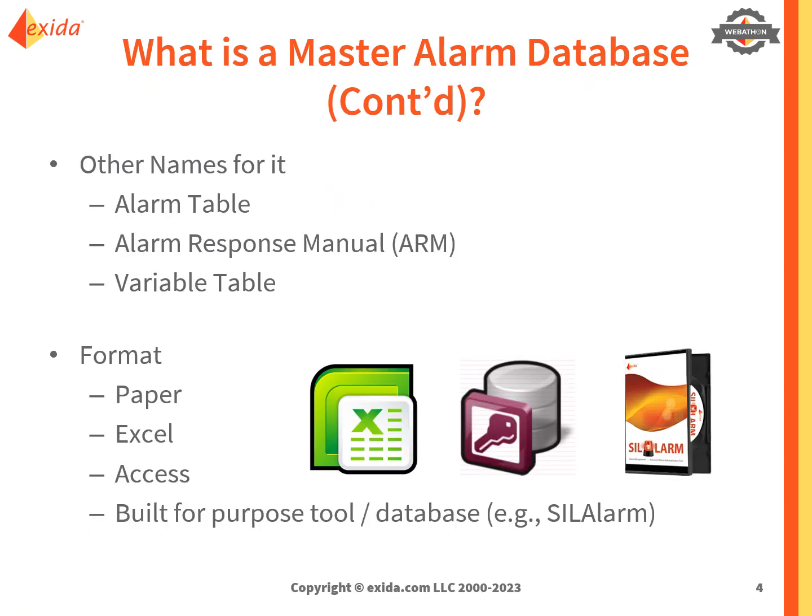Now, a lot of people call the master alarm database by other names, such as an alarm table, an alarm response manual, or a variable table. But one of the advantages of a standard is that it establishes an agreed set of references and names which everybody understands, and in doing so avoids ambiguity. Now, there's no requirement for the format of a master alarm database.